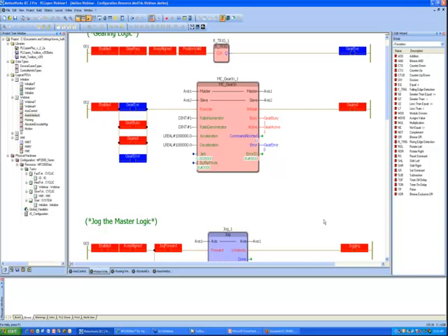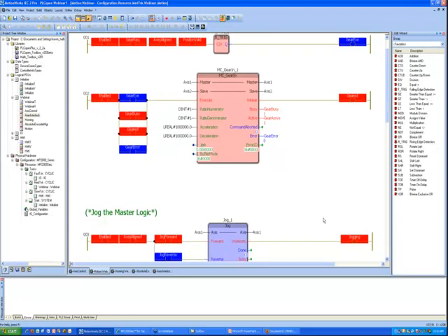applications where, let's say, it's a gantry that has X and X prime, so 2 servos running the same mechanical system. It'll work for either a linear or rotary application. In the case of a gantry, that's basically set for linear mode typically, where the axes are captivated on slides, maybe run by a ball screw. But we've had a number of other applications that would be rotary mode as well, that have 2 motors that share the same load. So this function block will work for those applications as well.